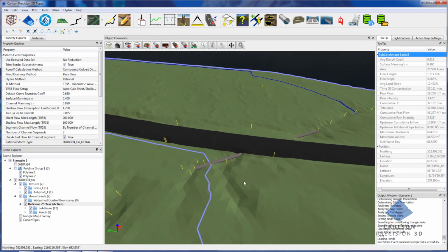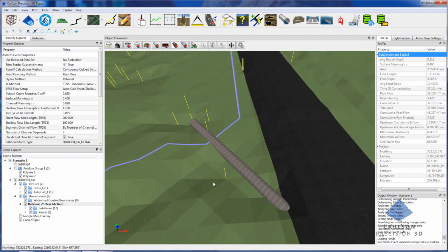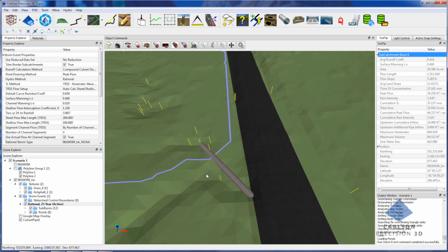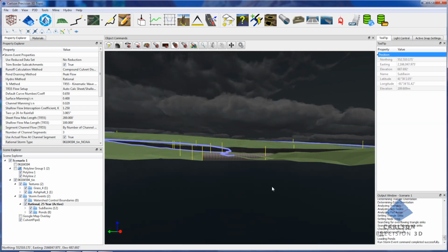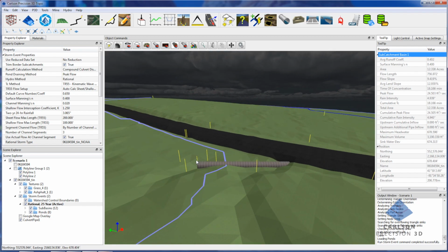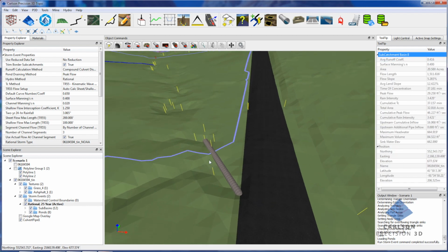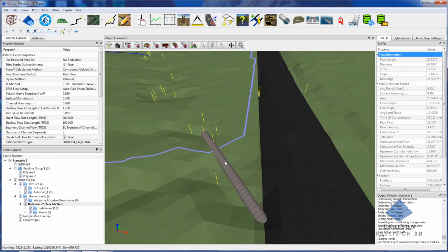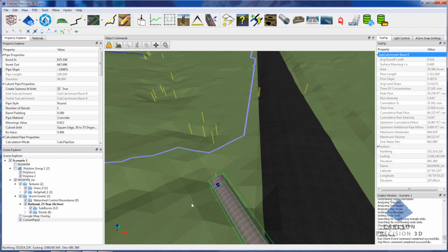And if you look at the surface carefully, you can see there's actually kind of a high spot in here. And if you know that that's not the case, then you can manipulate the surface and do a little bit more cleanup. So if you know differently, or if that really is a low spot ponding area here and a separate ponding area here, which you can see in a little better detail, then basically we could just do two culverts across the road, but it'd probably be more cost efficient if this channel was pretty much dug out and this pipe started from here.